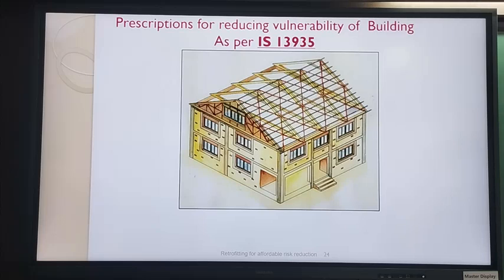Now, instead of a slab, if you had a roof with floor joists, timber joists, that whole thing will go like that, right? Okay. So in that, you have diagonal bracings properly done, with struts and everything, and that will also pretty much act like the way the slab will do. And it will transfer the shear through those bracings and struts to the end wall. Right? So that's diaphragm. Okay.